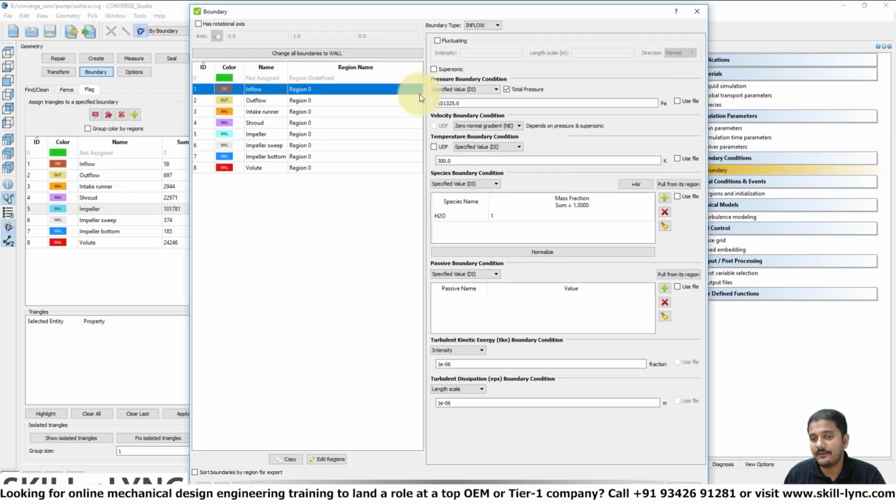At the inlet, what I've done is I've specified a total pressure boundary condition. Now if you're working in the oil and gas industry, or you plan to, typically when you get this type of simulation, you get accurate specifications for boundary conditions. Here we are specifying the pressure head that's available at the inlet of the pump. In this case, I'm assuming a total pressure of 101325, right?